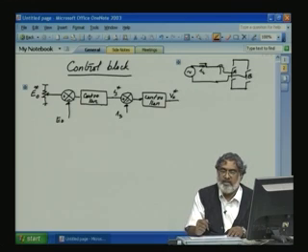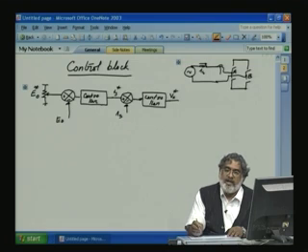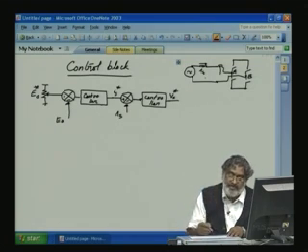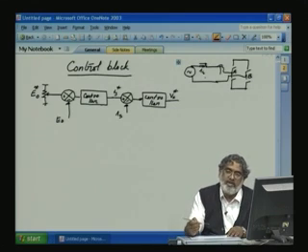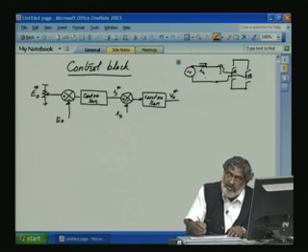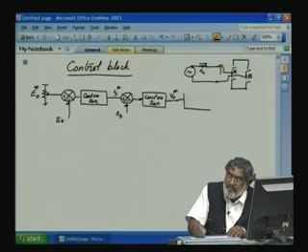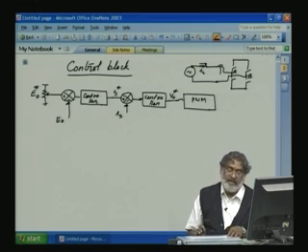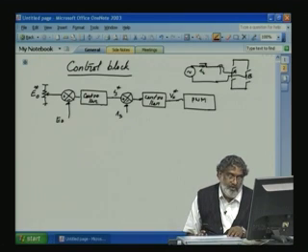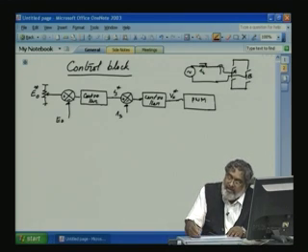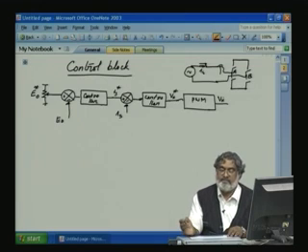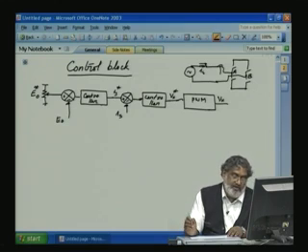The controller we take for only one converter; for the two converters, an appropriate gain of 2 we have to give at various places, but the same controller can be used for both converters. So, this is for VR star. This VR star will go to the PWM converter, pulse width modulation of the converter. So, the converter will give the correct VR. This is the reference value and the PWM will give the correct reference value.